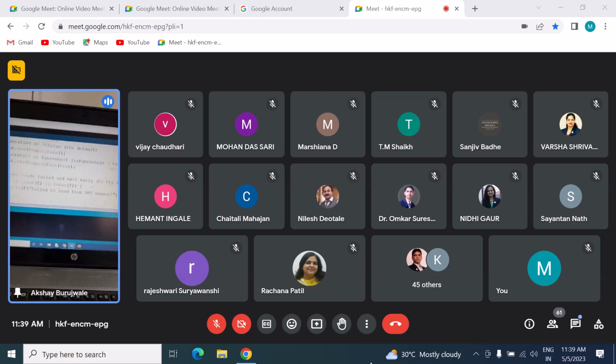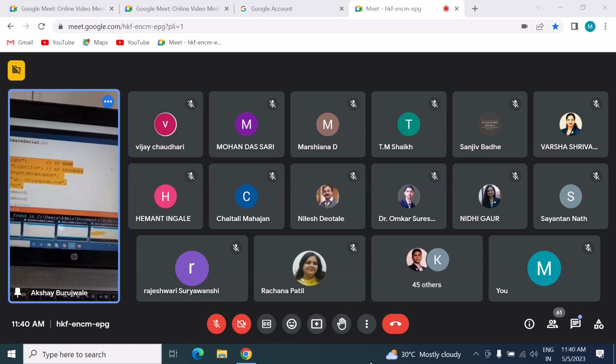You can upload your code by connecting with some Wi-Fi module, like how we see our temperature on ThingSpeak. So here is the simple code. We have to merge these two codes. The first one is with ThingSpeak, where we have settings like the light and the API keys, and we have to put in the other code of DHT11. If we make the correct combination of these two codes, you can upload your DHT11 sensor values to ThingSpeak.